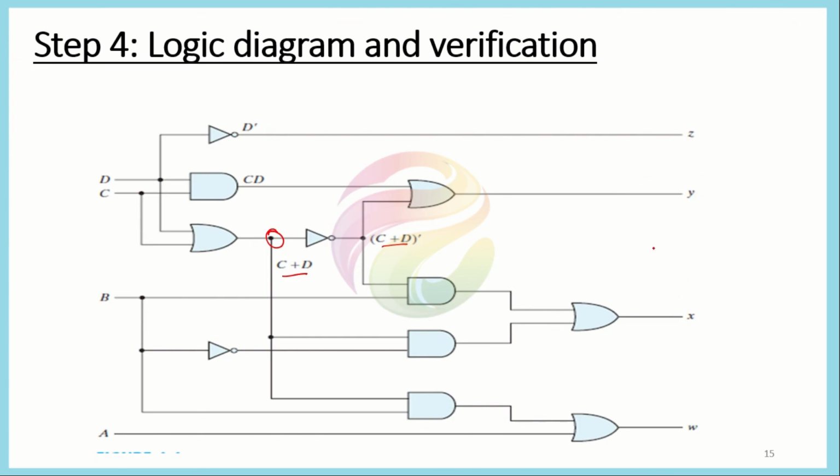These now represent the code converter outputs. We have inputs here as A, B, C, D, which means we apply a binary equivalent code here, and this whole circuit will generate the equivalent excess-3 code at the output. So this is a complete example of a code converter from BCD to excess-3.